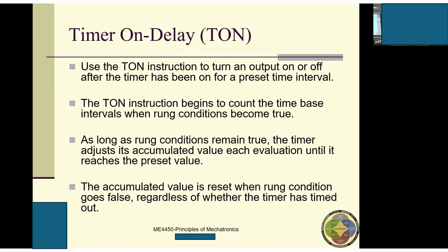The most important thing for this slide is that I want you guys to know how the TON is triggered. TON is triggered by a false to true transition. We have two different transitions. One is false to true, going up. Another one is true to false. I'm talking about this edge. So be very careful. We are engineers, and we should pay attention to these details.